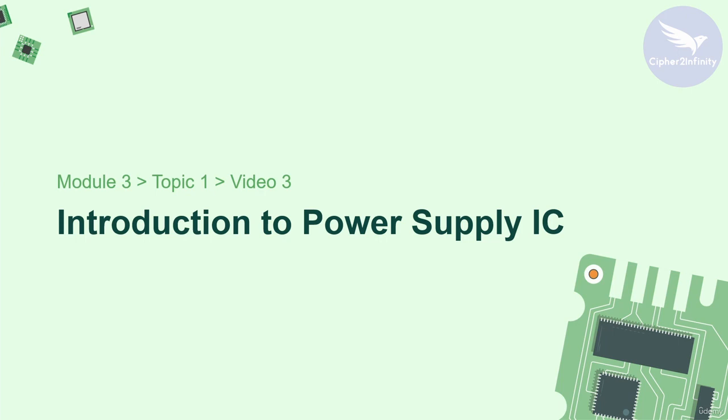So in the previous video, we did the power budget calculation and we reached two different conclusions. The first one was that our power supply should provide 5 volt on the output side and it should be capable of delivering 422 milliamps of current. Okay, so that was basically the first conclusion.